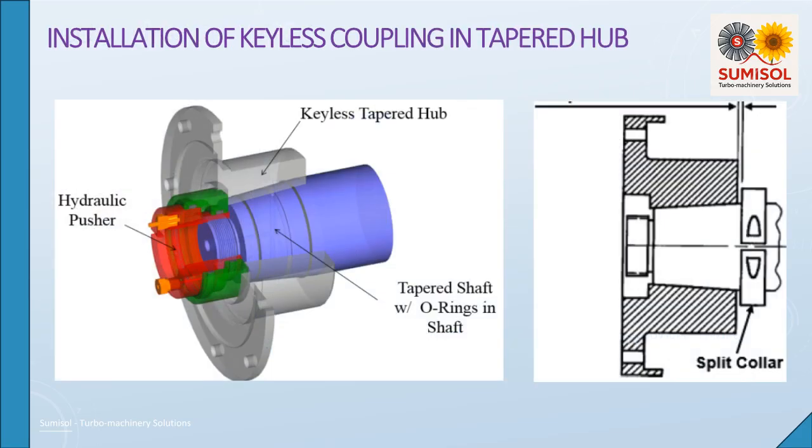Modern turbomachinery rotors are fitted with hydraulic taper bore coupling hubs. Coupling hubs must grip the shaft tightly. This gripping is accomplished by advancing the hub on the tapered shaft a specified amount. To facilitate this advance, one must expand the hub bore. When hydraulic pressure is used, a few specialized tools are needed. Basically, they are an installation tool, a high-pressure oil pump with pressure gauge, and a low-pressure pump with pressure gauge.